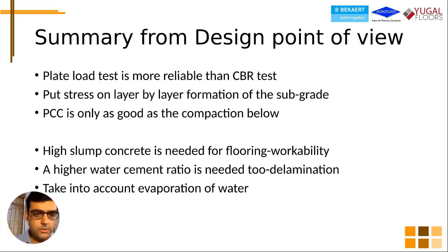So this is a summary of what I tried to talk to you guys about today. Plate load test is more reliable than CBR test. You should insist at site on doing layer by layer formation of the subgrade and not just dump material in one go. BCC should be reconsidered, because it is only as good as the compaction below. As flooring contractors, we need high slump for ensuring workability, we need to take care of delamination, and we also need to consider evaporation of water.